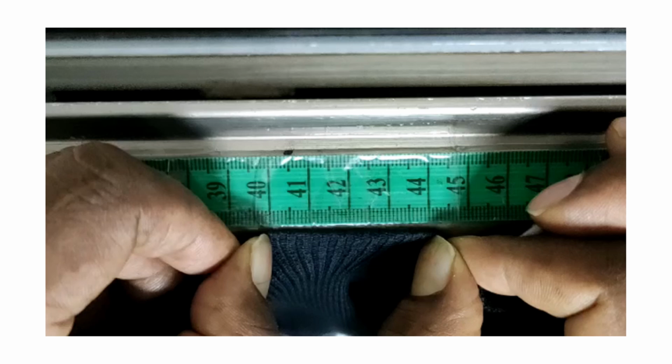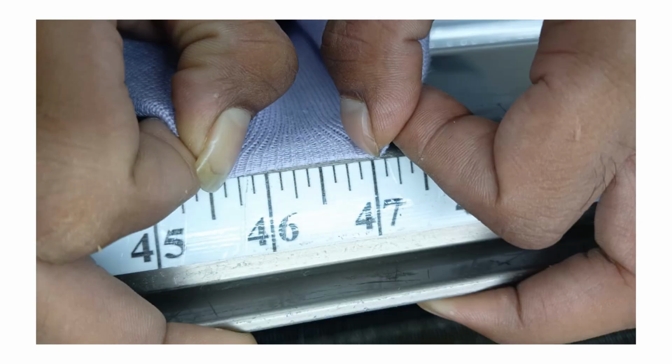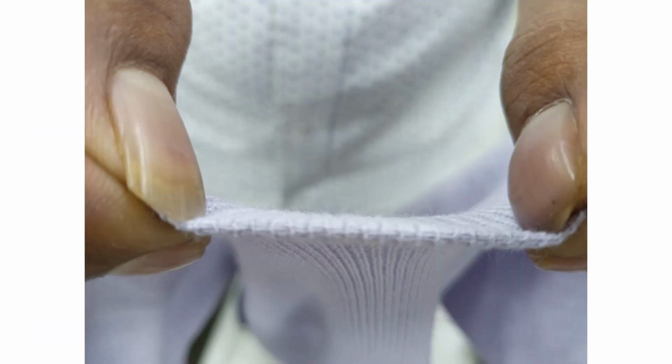But operators in India, Bangladesh, and even in some other countries do try to calibrate the machines. Unfortunately, in the most undesirable way. They hold a few wales and stretch the knitted panel very hard, often distorting it to irreparable condition. Stretching is by no means a way of measuring loop length. First, one checks by stretching a panel that has already been knitted. There is no way this panel can be corrected. Second, stretching is no method to determine loop length. And thirdly, this method can distort the knit structure of the tested panel beyond any possibility of repair.